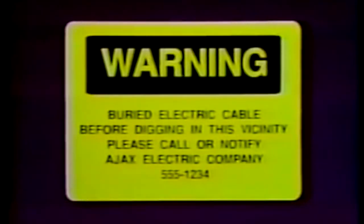The estimated location of utility installations such as sewer, water, fuel, and electric lines, or any other underground installations that may reasonably be met with during excavation work, are to be determined prior to opening the ground. Prior to start of actual operations, the utility companies or owners are to be advised of the proposed work and asked to establish the underground installation's actual location. When the utility or owner cannot establish exact locations or respond in a timely manner, the contractor may proceed with caution. Detection equipment or other acceptable means to locate utility installations must be used.